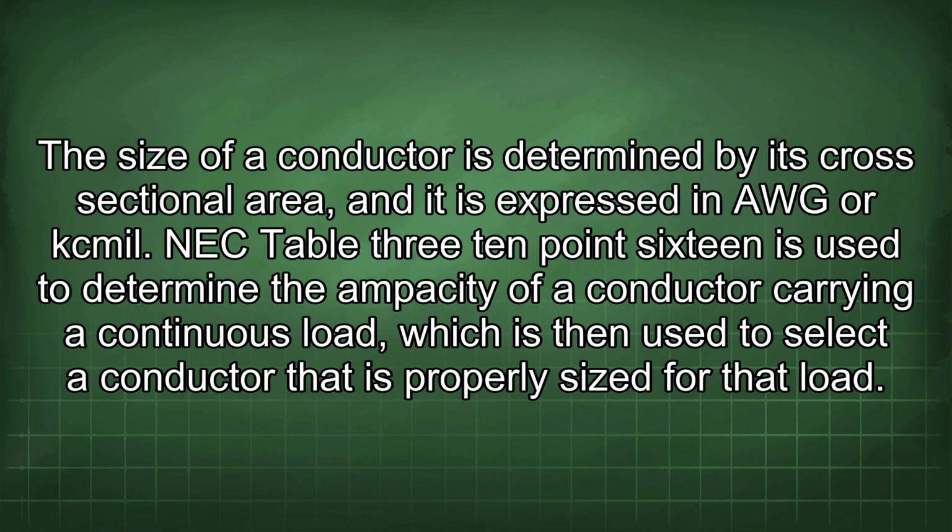NEC Table 310.16 is used to determine the ampacity of a conductor carrying a continuous load, which is then used to select a conductor that is properly sized for that load.